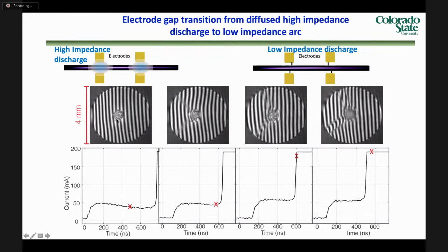So we interpret that a high impedance glow discharge immediately forms that carries this relatively small current from the filament to the electrode, and then after a while, full discharge arcs form. This high impedance glow discharge collapses into arcs that start linking the central channel to the electrodes. At that point, the impedance collapses, and you get this very large increase in current. And then, of course, the channels get more pronounced, and that's how the current is conducted.